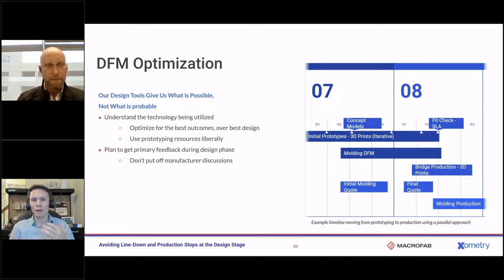So we were talking a little bit about materials up front, and this kind of falls in the DFM too. When I'm prototyping, the other thing I wanted to note is sometimes I am switching processes based on what my goal is. Right now this graph is biased towards plastic part production. But if I am testing a material, I can often match materials one-to-one, but sometimes it's not necessarily the material, but the property. So if you're trying to do a test for a fit or a snap, even though this item may ultimately be a material like ABS, if you speak with some of Xometry's engineers or look at our capabilities page, you may find that there are flexible materials that mimic those properties very similarly to ABS without actually being ABS. In fact, a lot of times it's materials like nylon, which print more forgiving for cantilevered features than a filament-based process, which is usually where you find ABS.